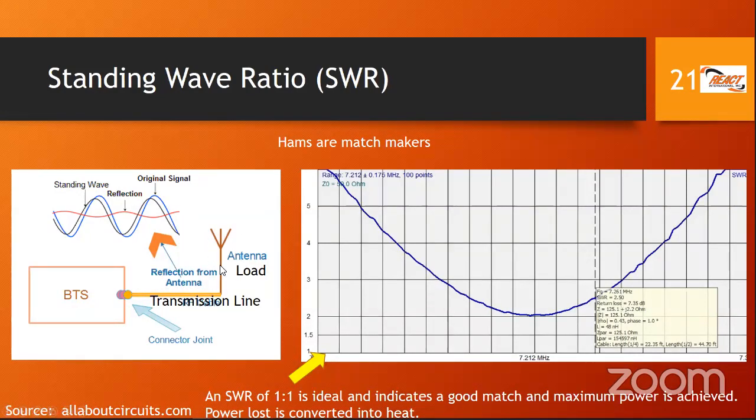And that's why we always talk about tuning our antenna so that the impedance at the point where the transmission line meets the antenna is at 50 ohms. And we want the property of that feed line to be 50 ohm. That's why when we are using cable for amateur radio purposes, we need a 50 ohm feed line and not 75 ohm, for instance, right?